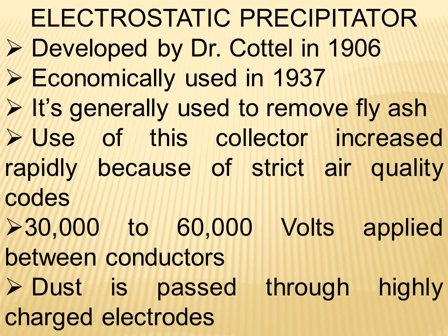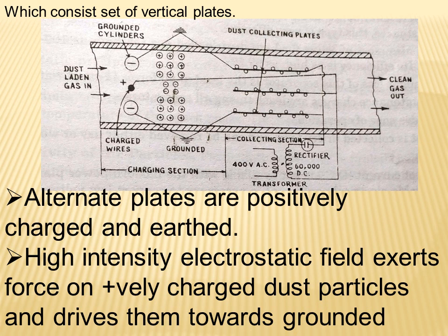It is often considered worthwhile to retain an existing cyclone as a preliminary collector in cases where collection efficiencies must be upgraded, especially where there is a large amount of unburnt carbon in the fly ash, about 15%. Because the presence of large quantities of carbon in the gas can adversely affect the collection efficiency of a precipitator.